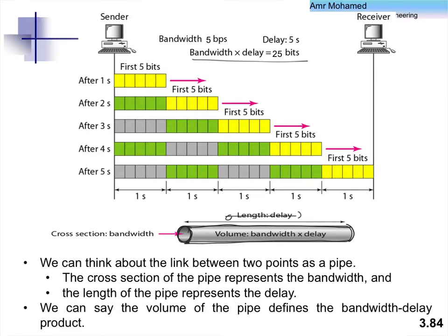There's the broadband transmission, where we have to convert the digital signal to analog using a high frequency carrier, and we use that to first align the properties of the transmitted signal with the properties of the transmission medium, because as we said, the transmission medium itself has a bandpass effect, right?